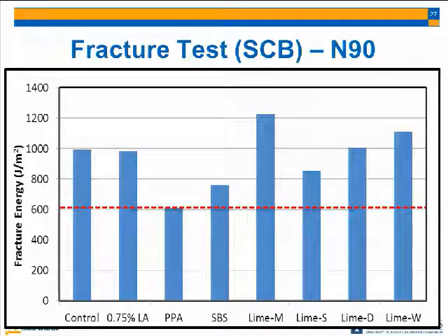So in warm mix, they actually heat the aggregate to the same temperature? Yes. The mix is at a lower temperature. You lower the temperature of your mix, but the aggregate is heated at the same temperature.